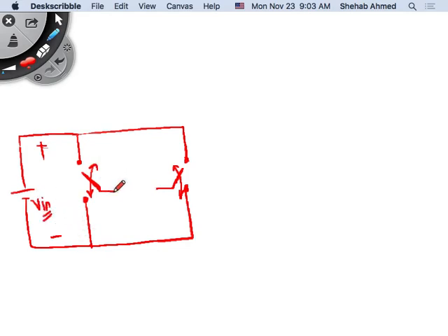And at the output, in the buck or the boost or the buck boost, I had the switch current going through an inductor. And it's the same here. I can draw this as half the inductor here, half the inductor here. They're in series anyway. And then this is my load for my inverter.